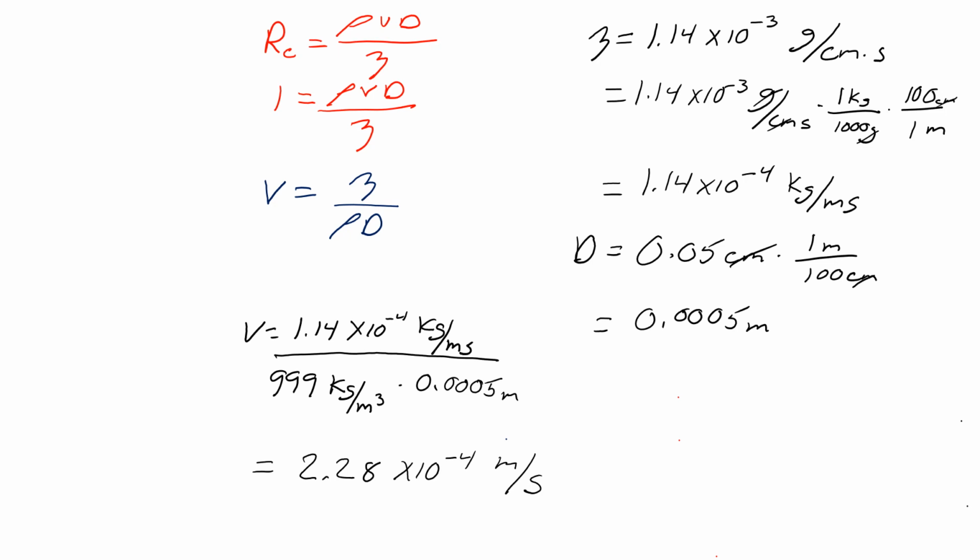And it works that way for groundwater too, but it's really hard to measure the pores in a rock sample. But we spent a lot of time studying grain size in rock samples, so we know those a little better. So we can modify this Reynolds number by swapping out grain size in place of pore size. And when you do that, the Reynolds number shifts so that the transition now is at 1. Anything less than 1, it's flowing laminarly. Darcy's law is valid. Anything over 1, it's flowing turbulently. Darcy's law is not valid.